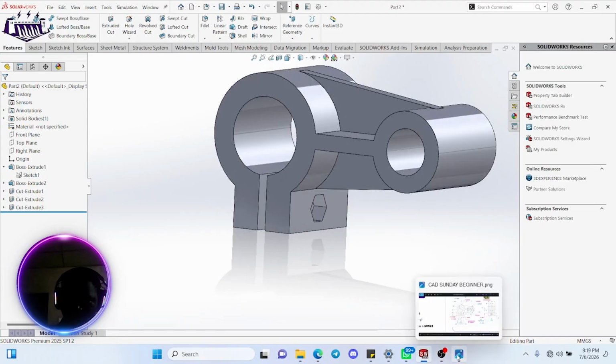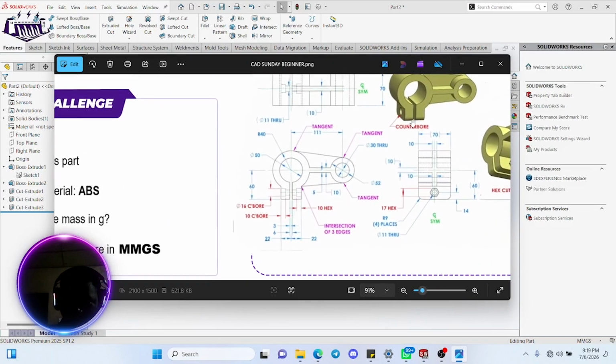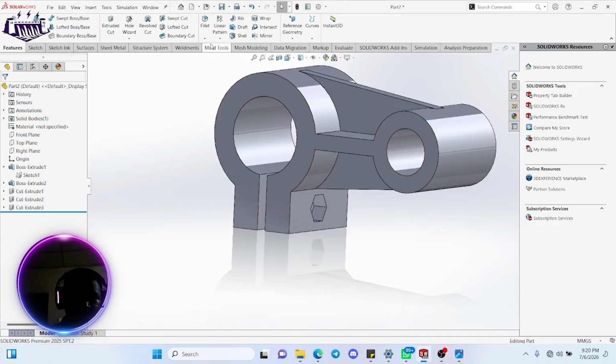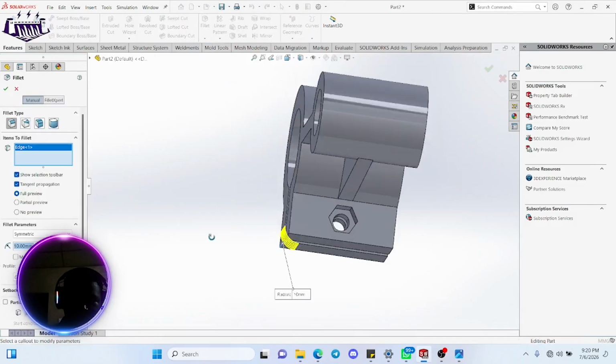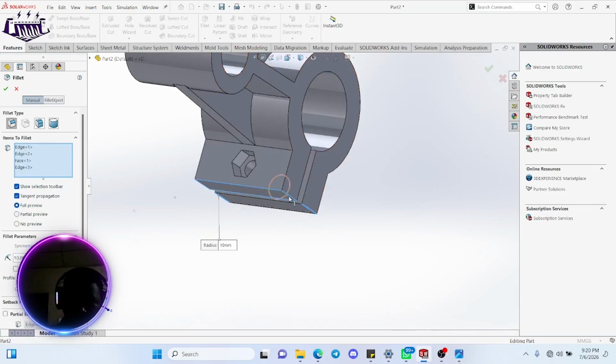Now when you look at this sketch properly, you can see that the 3D gives you a better view. There are filleted edges here. So for those filleted edges, you need to check what's the fillet here. Fillet is of radius 9. So you come here and then Fillet, you click here, you click here as well, sorry, pardon me.